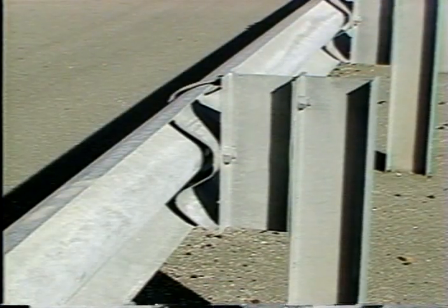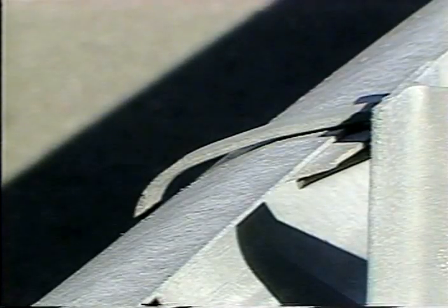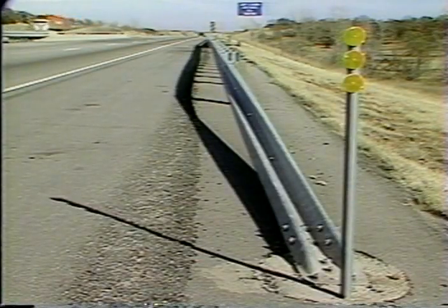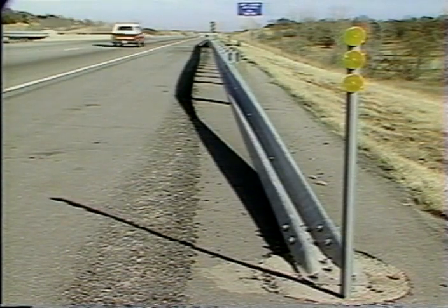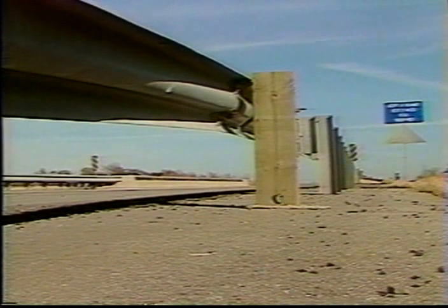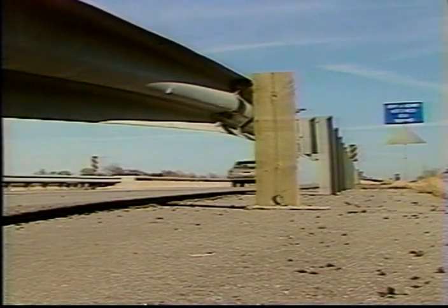To set up the system, a short section of W-beam is bolted to the posts. The barrier railing is then placed into this section and rigged to be held there by a weak galvanized steel clip over the top rib of the rail. Any significant downward load on the railing, such as the weight of a car, pushes the rail down from this connector and allows the W-beam to fall harmlessly to the ground. The impacting vehicle then either continues on to shear off weakened posts or until it decelerates to a stop in a runout area behind the rail end treatment.